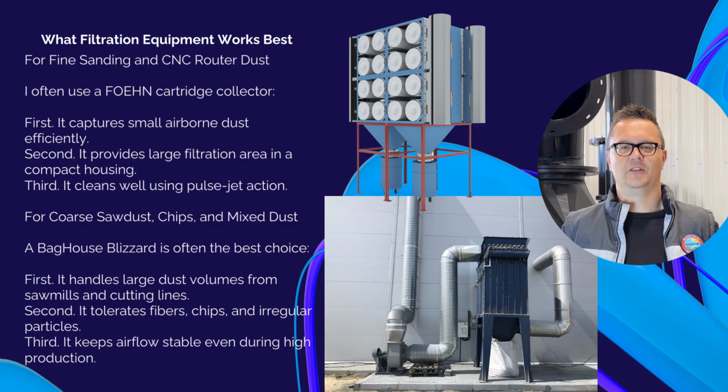For combustible dust hazard, I include, first, explosion vent panels sized for the collector. Second, grounding and bonding of all ductwork. Third, anti-static filter media. Fourth, spark detection systems upstream of shredders or planers. Fifth, isolation valves in ducts. Wood dust safety cannot be ignored.